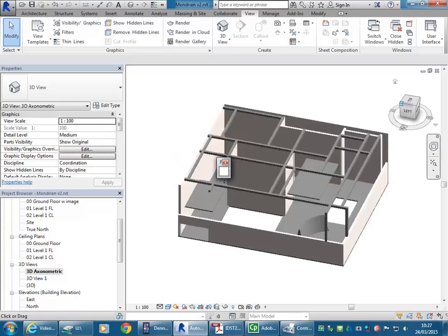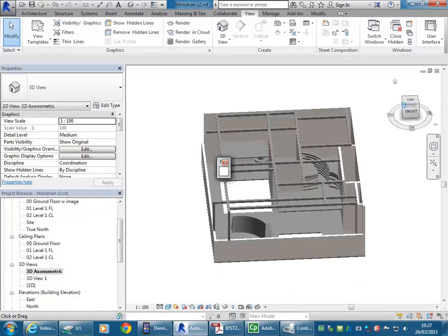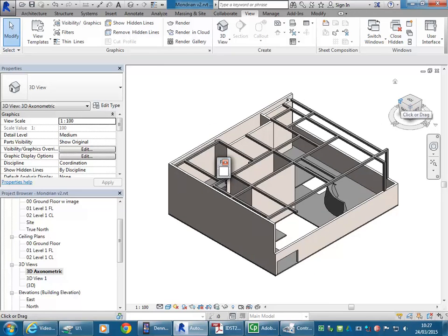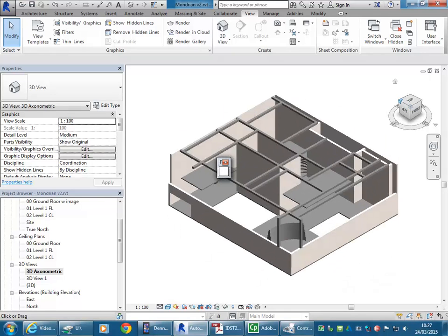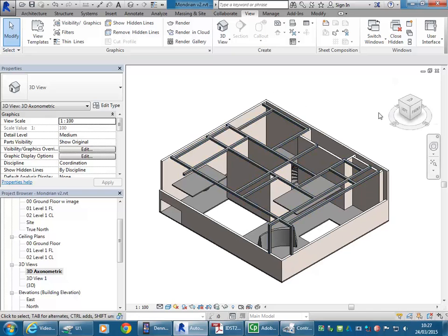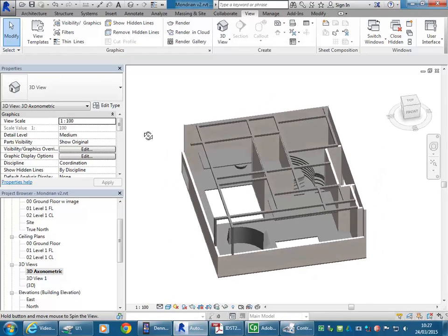And you can go and click through the other corners, and it will give you exact 45-degree views, which are really useful for architectural and interior design drawings. Close this thing. And also, because you only need to have an axonometric, you can try angles in between, if that is more appropriate for your design.